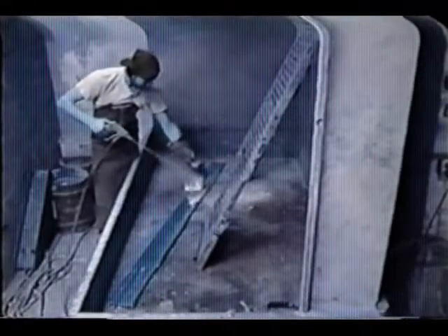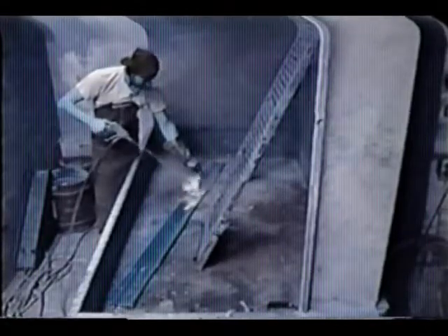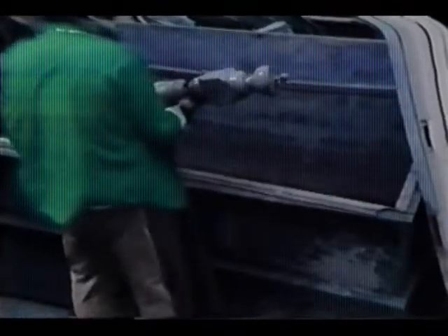In cases where contaminated wood is of architectural value, it can be treated by off-site paint removal. Off-site paint removal involves the removal of the component, off-site stripping by a commercial paint stripper, and reinstallation. Components that are likely candidates for this treatment include doors, windows, trim, and other removable components such as decorative stair railings. The process begins with the careful removal of the selected components.